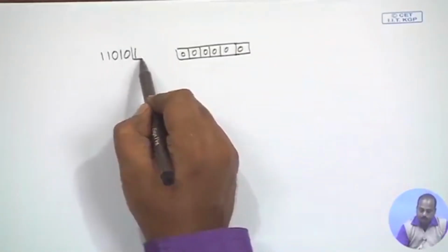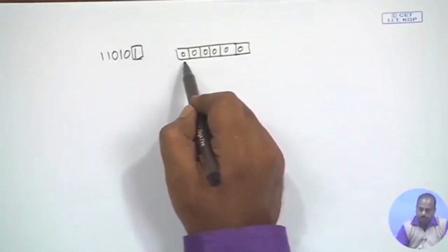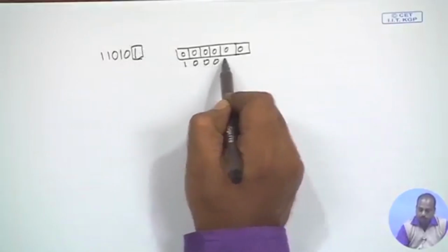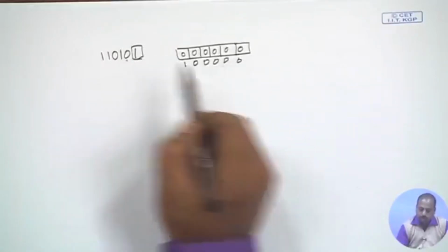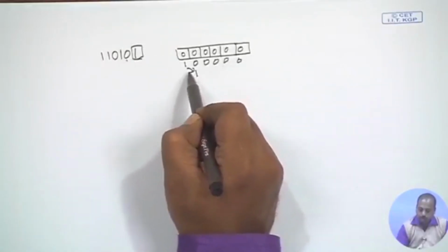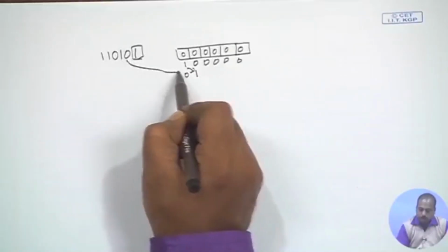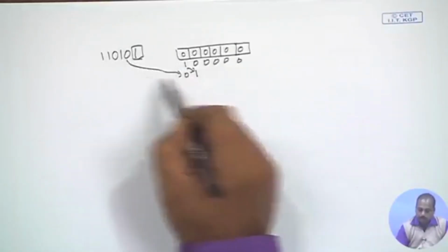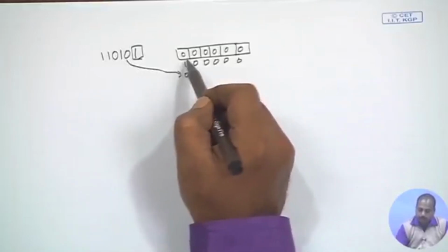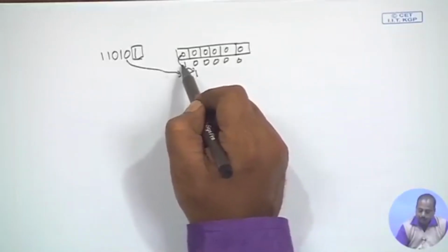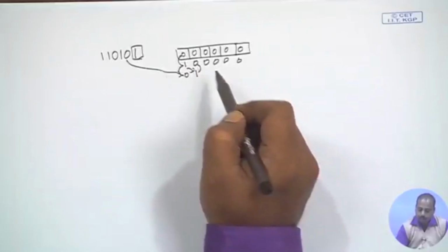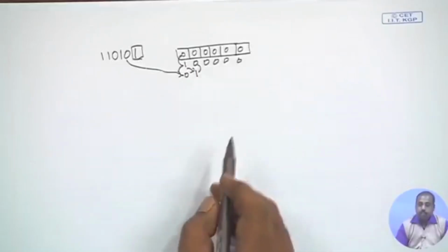Now, first this 1 bit will be shifted into the scan chain. So, it will become 1 0 0 0 0 0, then this 0 will go. So, this 1 will come here and this new 0 will go to this point. You see that this process will continue, and there are transitions like this: this cell I have already seen 2 transitions, this cell I have seen 1 transition, and again this way there will be transitions.